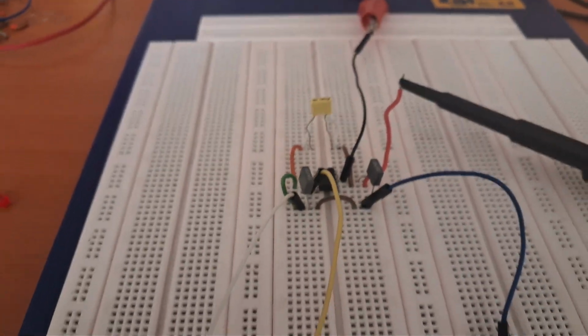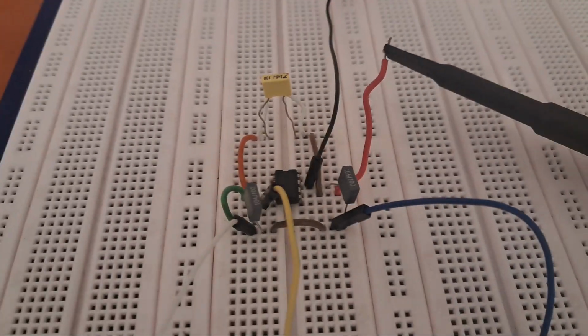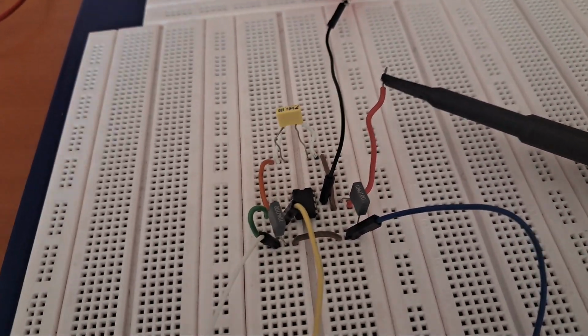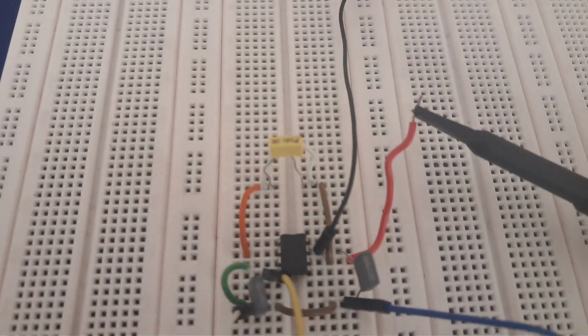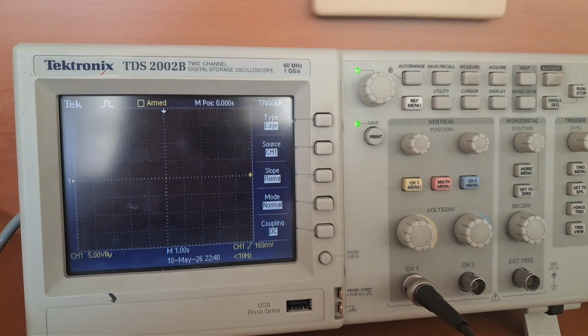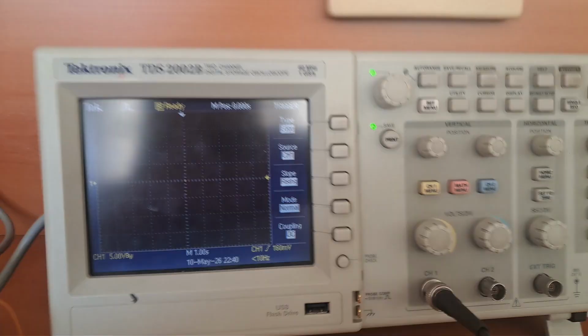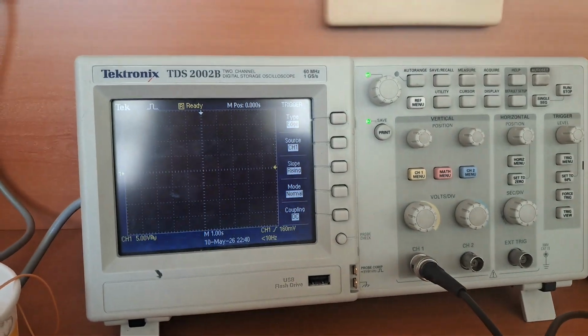And now I'm gonna actually repeat the same measurement. We're gonna get a ramp, and we're gonna find the slope of it, and then we're gonna multiply it by the capacitance. Now I push the single sequence button. Now we're waiting for it to be ready. Now I'm removing my shorting wire, and we're waiting.